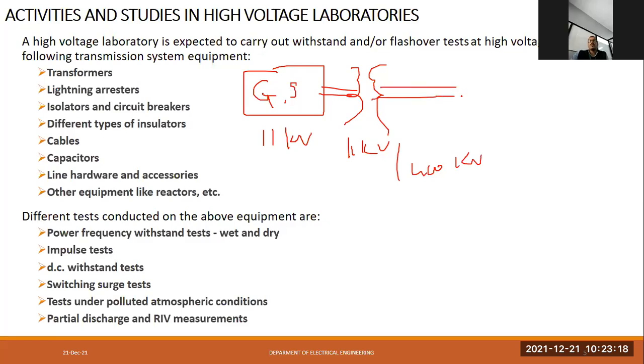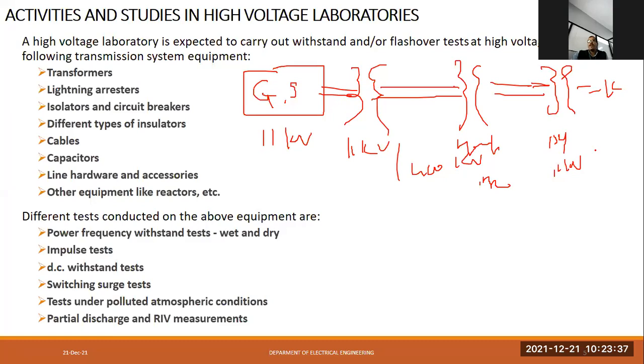Then it comes to our district level substation, and here it needs to step down from 400 kV to 132 kV. Then when it comes near our tehsil, or near our home, the 132 kV needs to be converted into 11 kV. And again that 11 kV will be converted into 440 volt, and then this is given for domestic use, or agricultural purposes, three phase 440 volt. So this is the simple transformer, the equipment used in the transmission system.